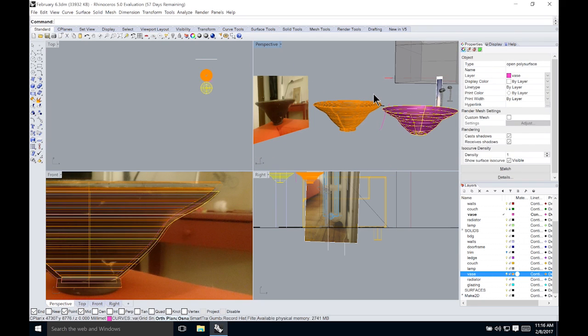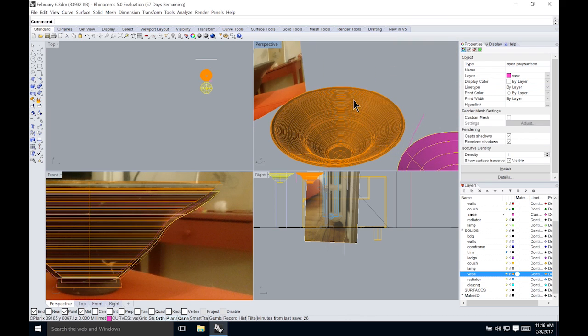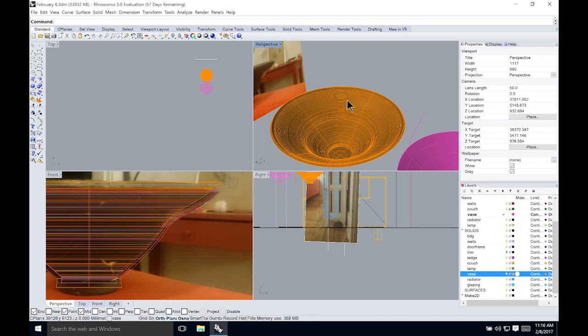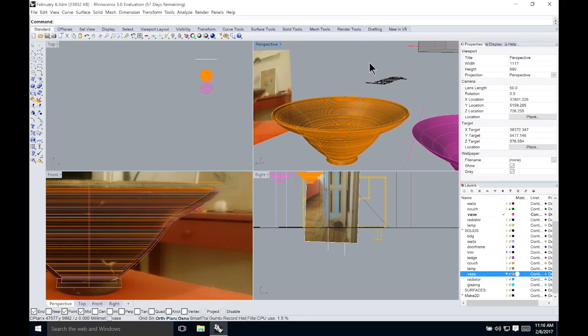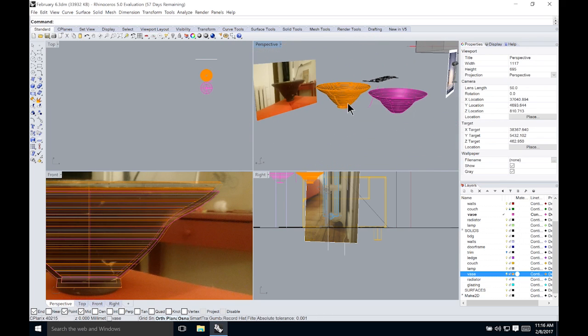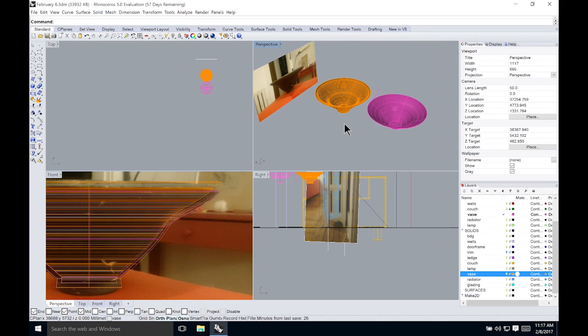Why that's important is because depending on how big or prominent this vase is in my drawing, I might or might not want to give it a thickness. Because if I do and then create a 2D drawing, there will be more edges showing up, and potentially just a bunch of lines that, printed really small, do not look very nice. So modeling too much sometimes leads to having to clean things up.